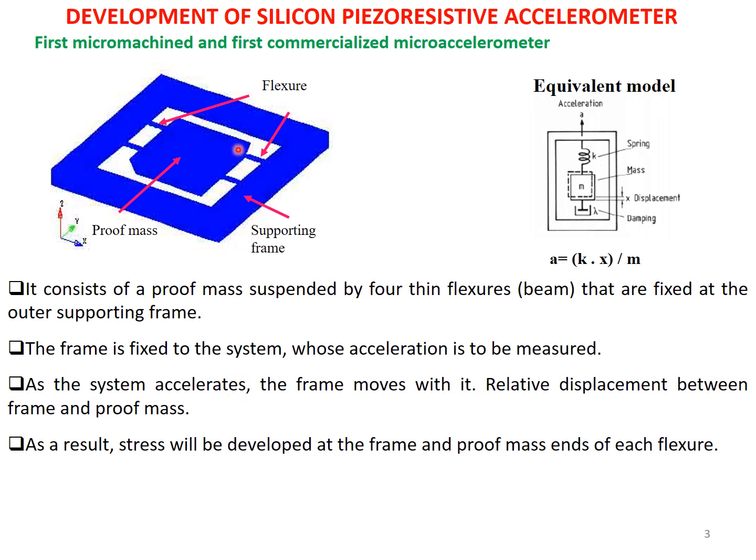And since the mass spring damper system is inside this frame, that means attached to the frame, this displacement will be transferred to the mass spring damper system as well, and obviously there will be relative displacement between the proof mass and this reference frame. Because of that relative displacement, the proof mass will be moving, and the spring will be experiencing some sort of stress or strain, basically tensile or compressive force.